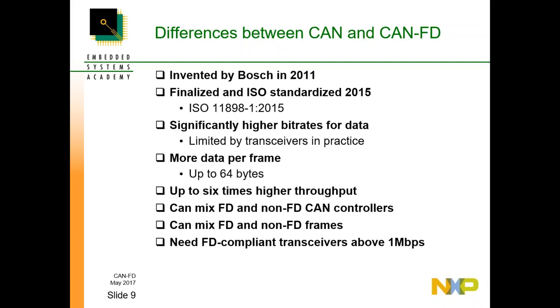This means that there are 2 versions of CAN-FD, the old version and the ISO standardized version. It's possible to use the old version with the LPC5461x, but it's not recommended for new designs or production going forwards. The ISO version is the only one to use, really.